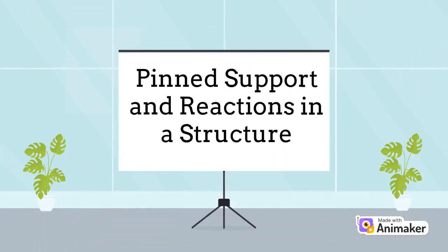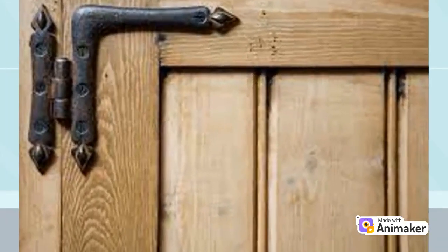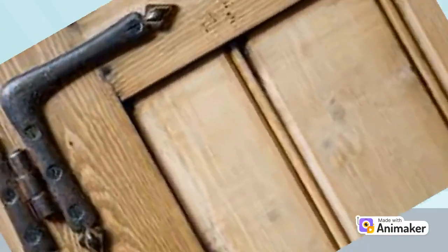Pinned support and reactions in a structure. Pinned support or hinged support can resist both vertical and horizontal forces, but they cannot resist moment. It means hinged support is restrained against translation. Using equations of equilibrium, one can find out the components of horizontal and vertical forces. The best example for hinged support is a door leaf, which only rotates about its vertical axis without any horizontal or vertical